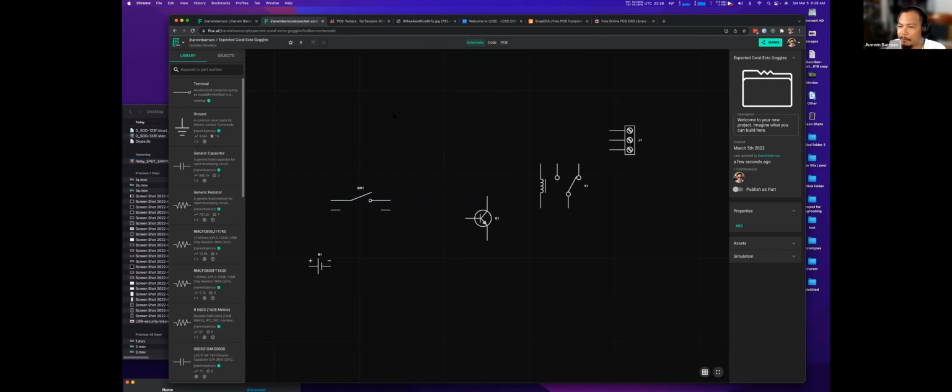As you can see here, these are my favorite sizes, 0201 up to 0805, because those are the only things that I could solder by hand. So those are my favorite, but I'm going to stick with the 0805 in here. As you can see, these are not specific.